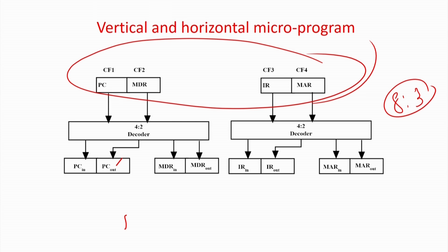The motivation is that in each cluster you should not put signals which are required to be one simultaneously, but it may not be easily solvable, because if you go to the level where we keep individual bits in a cluster which can never be one together, then you will go to a fully horizontal microprogram where each bit is independent. So we can try to think that in a very high number of microinstructions, which signals are to be one at one point of time,